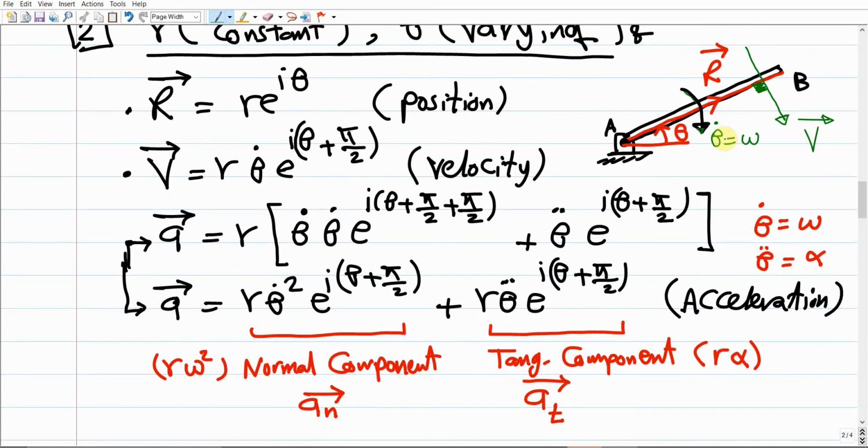So if we consider this direction, and let us assume that this is the direction of rotation of both omega and alpha. What is omega? This is the angular velocity. What is alpha? This is the angular acceleration of this length. If both are rotating in the same direction, the tangential acceleration is in the same direction as the velocity. But how about if alpha goes in the opposite direction? This happens basically in case this length slows down.